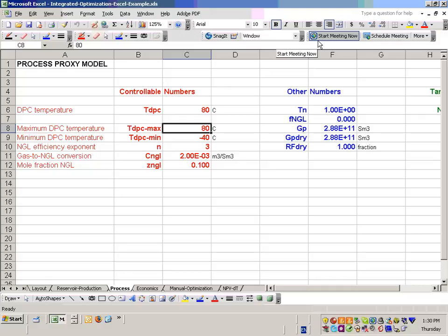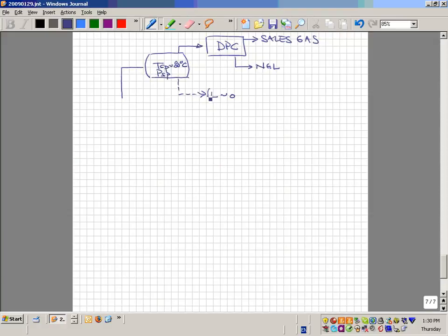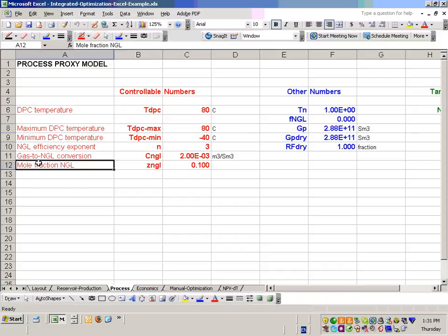Now you could easily change this problem if you want to make it into a gas condensate. But if you bring in a gas condensate where there's a significant amount of condensate coming out here, then that amount would vary as a function of average pressure, meaning time. Once the reservoir goes below the dew point, the amount of that condensate would be changing with time. So we would have to introduce a time variable process, and I didn't want to do that in this project. I wanted to keep it relatively simple. But you could introduce a condensate where you bring out a product, with another mole fraction of condensate, maybe constant, independent of the surface processing. But for this problem, we're going to make it simple.